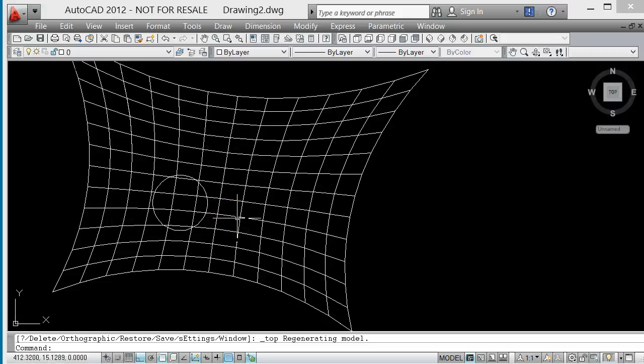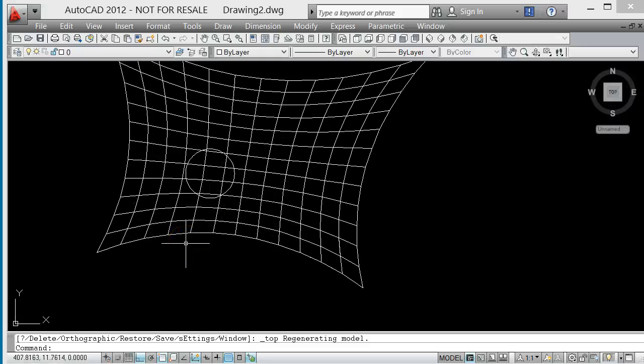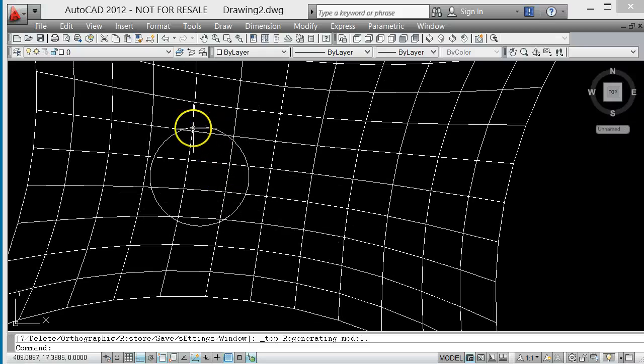As long as the hole is relatively small compared to the whole mesh, all that we have to do is assume that the mesh, that is the shade sail, takes the same shape that it would take if the hole wasn't there, and just project this circle onto the mesh as a shape that we can cut out to obtain the circle in the production version.